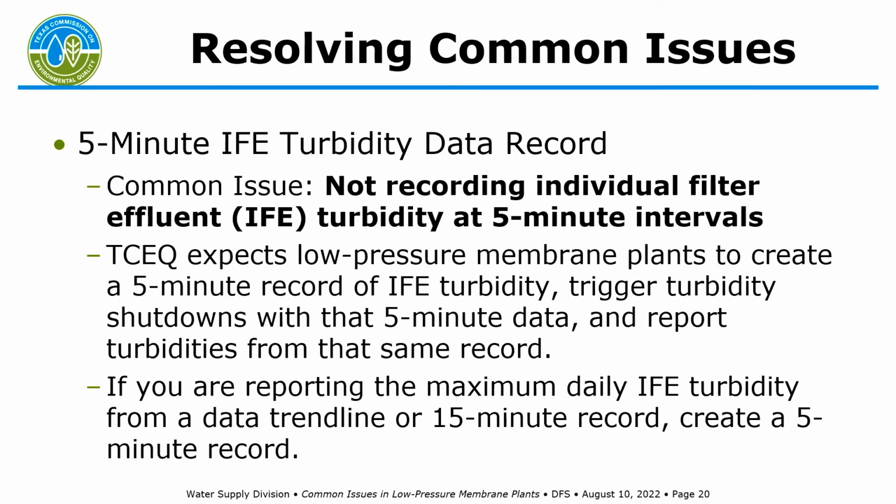Another issue. For IFE turbidity on your membrane units, not recording the individual filter effluent turbidity at 5-minute intervals is a compliance issue. When we wrote your approval letters for the membrane plant, we expected that you would be creating a 5-minute record of IFE turbidity throughout the day. You were using that 5-minute data to trigger turbidity shutdowns and report data to us from that.